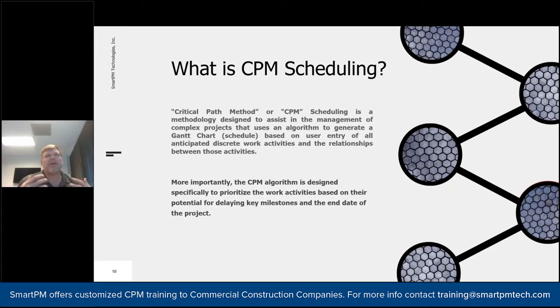But if you're just drawing out a schedule and putting it over time, and not doing that additional math to understand the longest, critical path, what is the most important, second most important, and third most important activity going on today that has the highest risk of delaying the job, then you certainly don't have what you need to make crucial decisions about resource constraints. In construction, a common issue is not having enough people, and knowing which activities have a little room for delay and can be pushed off to a later date, versus which activities need to get done today, come hell or high water.